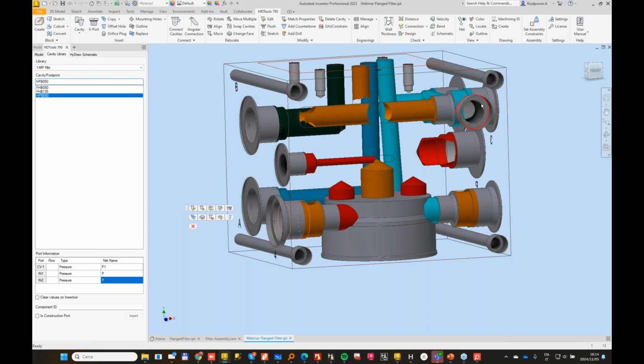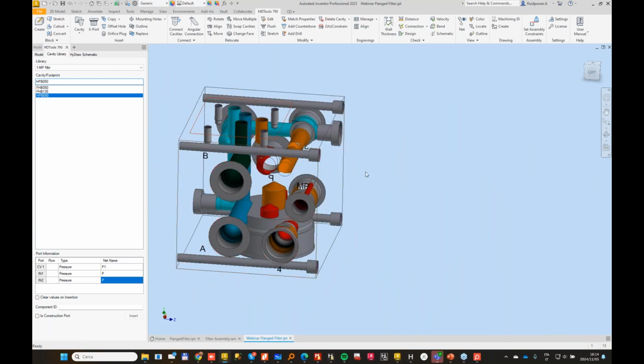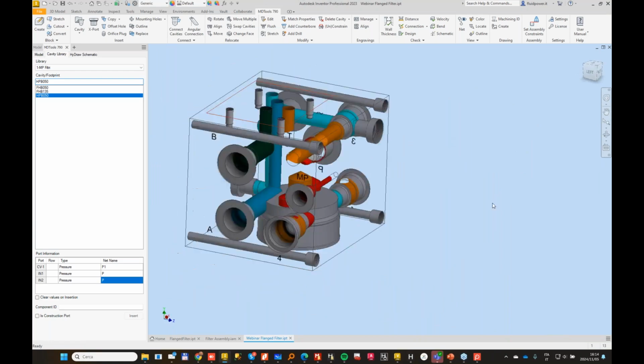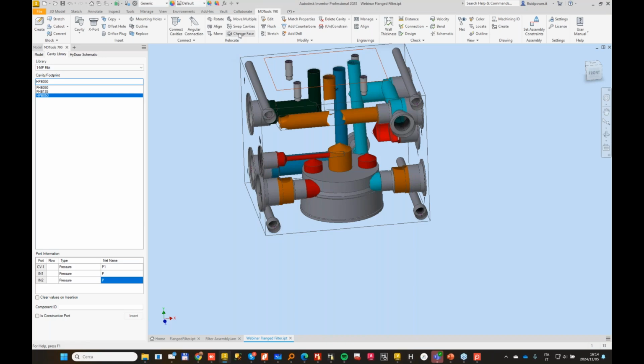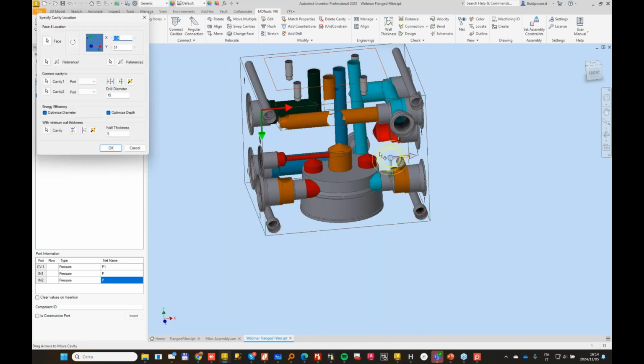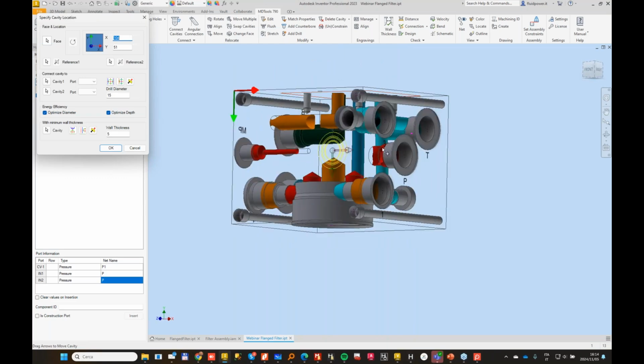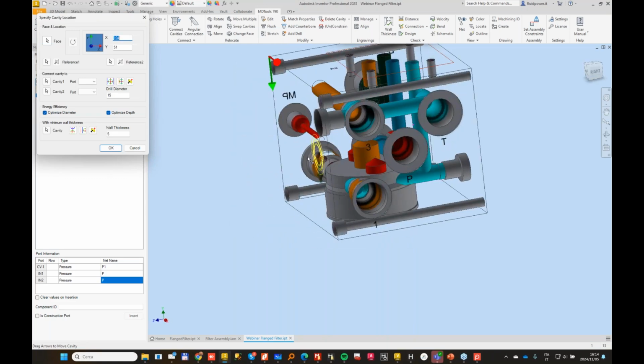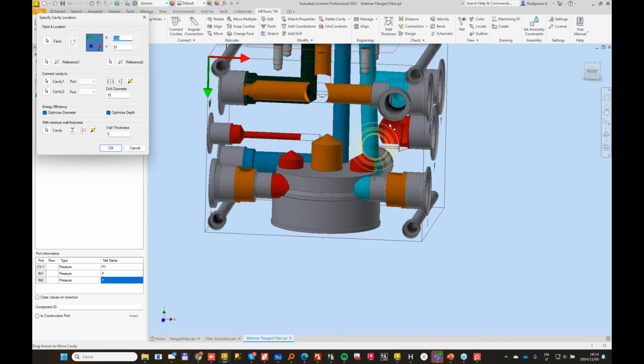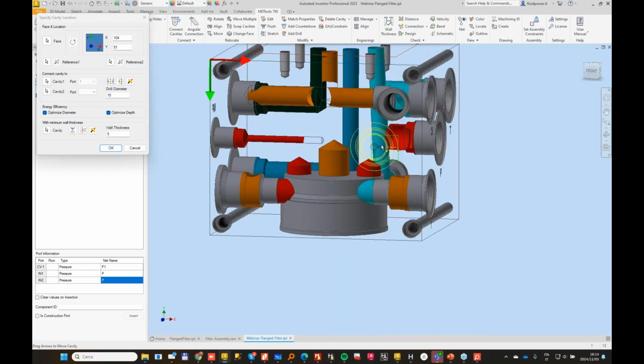Now that we don't have anymore the filter on this face, we have all this face free for components. And although my intent is to limit the total width of this block, I can accept, as a designer, to have my cartridge valve here. The check valve normally does not have a long impact in height. So I just change phase and do a connection with the same cavity.